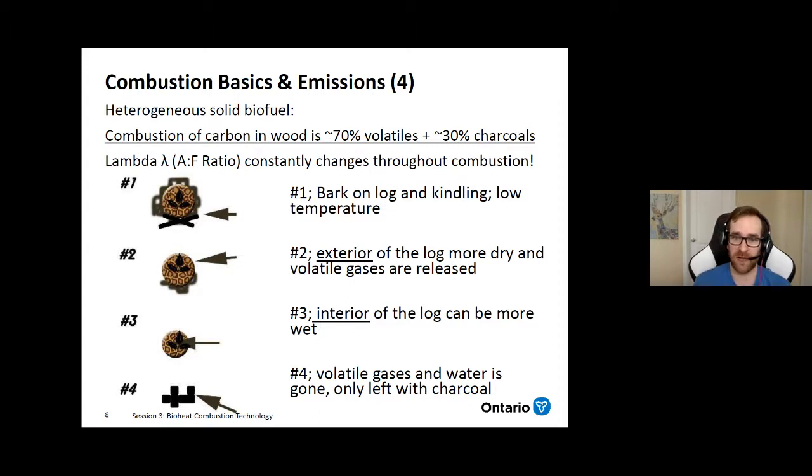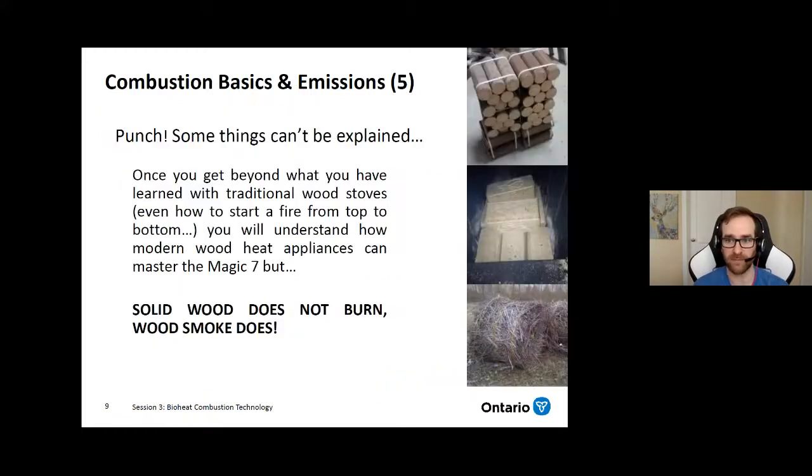So it's key for any of the systems that are burning in a batch that you try to monitor where you are in this step, because as a fire burns, things change all the time, and the air to fuel ratio is just going to be out of whack, and you're not going to be able to maintain proper combustion. And that's the thing that's hard for people to understand: the wood itself doesn't burn. It's the smoke that's contained in the wood that does.